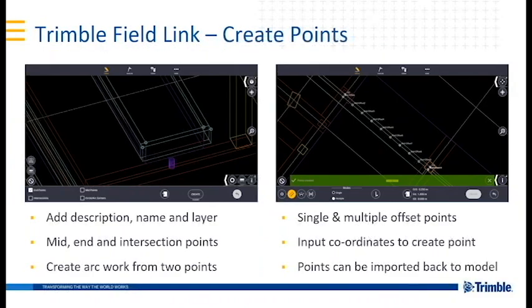You've also got a lot of flexibility of what you can do with this data and this model when you're out on site. So if you're only creating small points, you don't need to do that prep side in the office. You can push your model straight into the tablet, and you can do your points like you would in any CAD platform. You can do midpoints, ends, being able to snap onto objects. You can do offsets as well, and lines, and these points are very, very easily created. Once you've created these points as well, they're going to carry over into your BIM model. So when you carry these back, all this information is going to be there. And you can have a setting, so when you import these models, it'll flag to your CAD guy any new points you've created or anything that's been set out of tolerance. It's going to make it obvious to him as well.